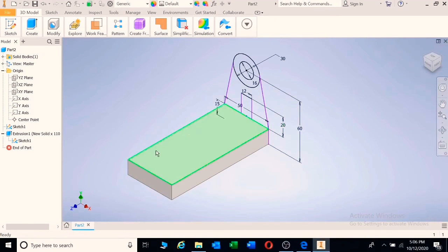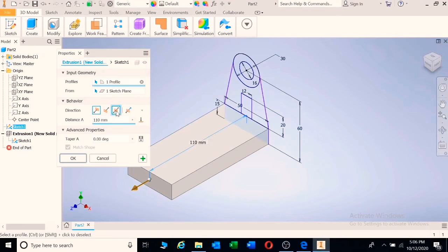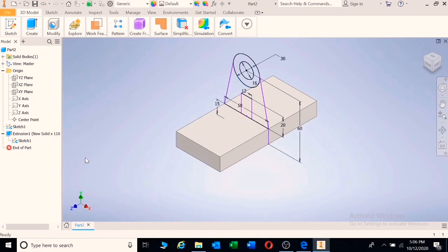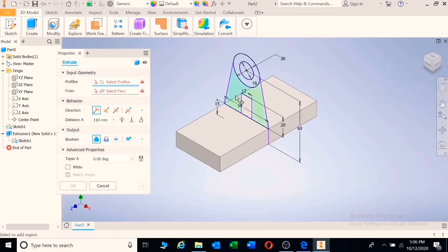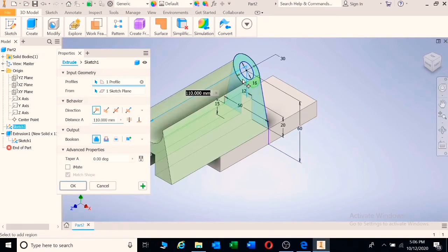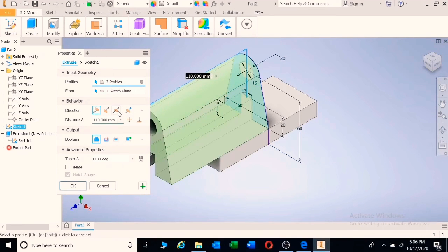So to extrude in that direction will make you extrude to that point, take a material away, extrude to this point, and then take material away, then you will have that. But double extrude is easier. So I'm going to double click on my extrude and click it on double, or symmetrical extrusion. I'm going to say E for extrude. I'm clicking on there and there. And I'm going to go double.